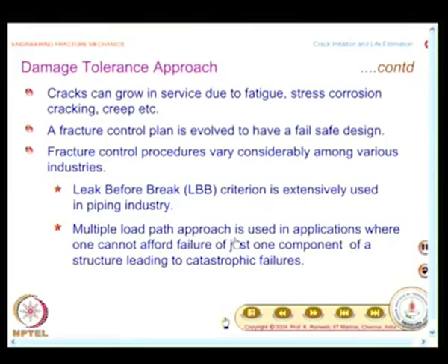And also, in the case of fracture control, when you have welded structures, provide deliberate crack arresters. If you have a riveted connection, the riveted connection itself serves as fracture control, because you have holes. When the crack comes to a hole, the hole acts like a delay in re-crack initiation. Such a luxury is not available in the case of welded structures, but welded structures also have to be protected.